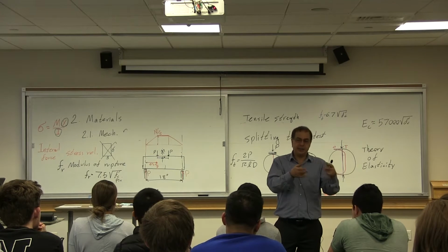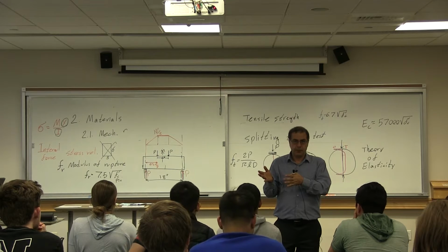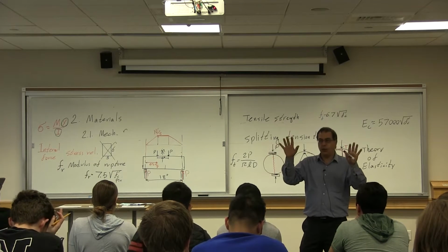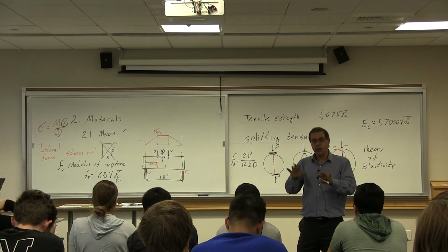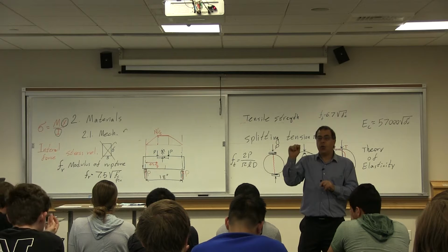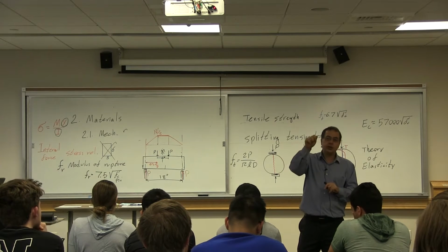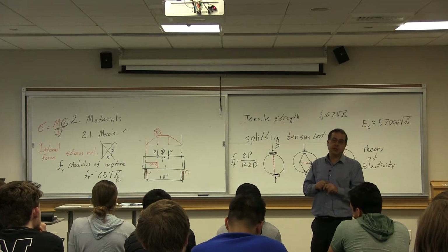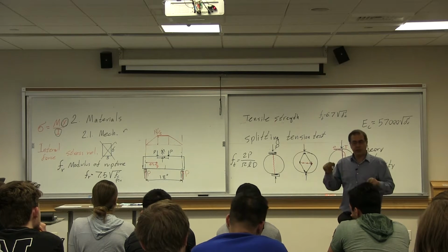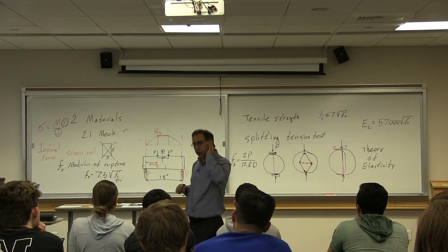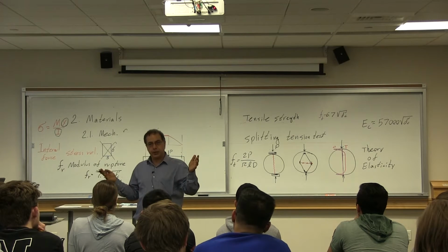Can we find them is a different question. But the number of equations and number of unknowns are always exactly equal. It cannot be one more or one less. The only question is, what types of equation are we talking about? So what type of equation did you use when you looked at statically determinate structures? Global equilibrium, or general equilibrium equations.